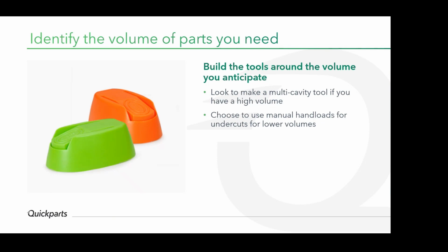The only thing is the tool life is lower, so you can make 2500 parts off of those tools typically, but that is very cost effective and fast. So you can quickly get parts to the market, test your function. That actually accelerates your product development.